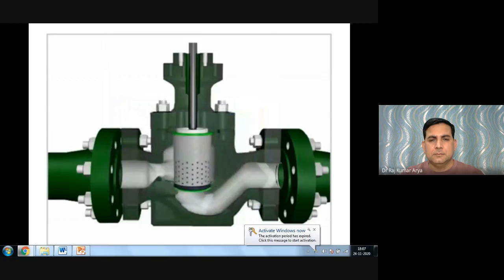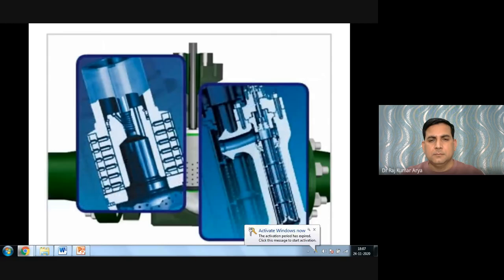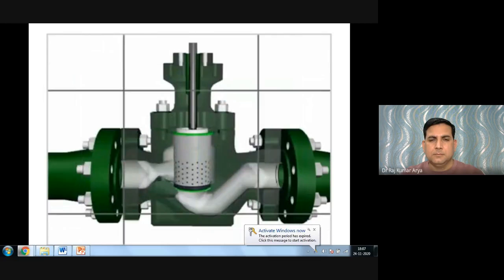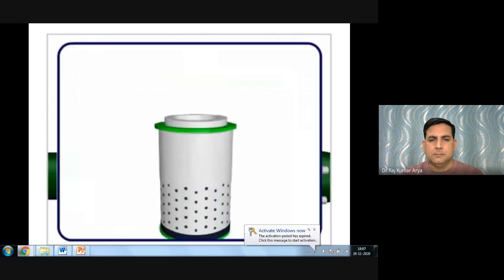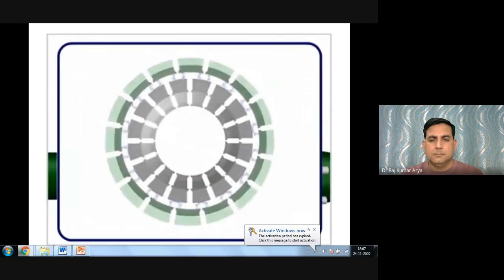Pressure drops are staged by the use of expanding nozzles or expanding flow areas. For example, in the Cavitrol 3 valve trim, nozzles have holes shaped to manage flow separation. Multiple small holes shift the noise to higher frequencies.